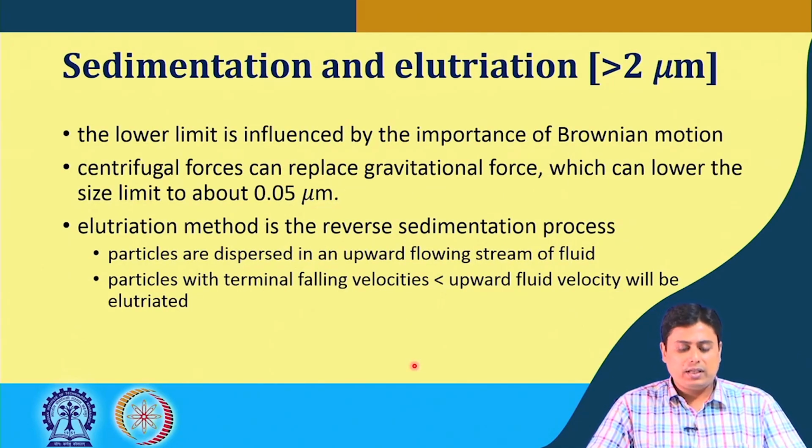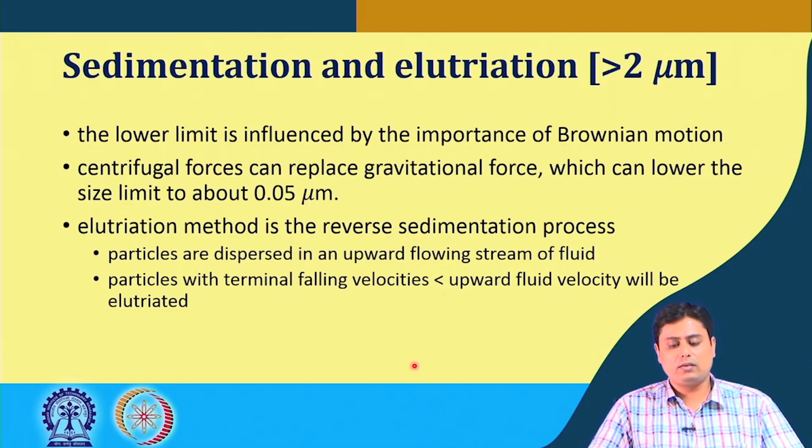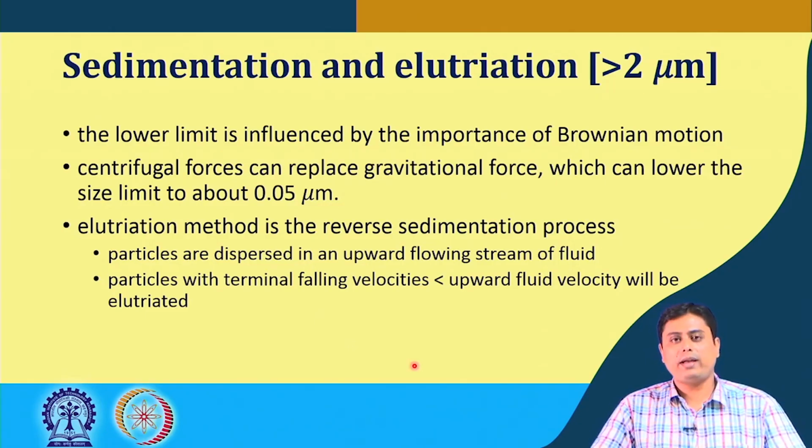The lower limit in this case is influenced by the importance of Brownian motion, because as we decrease the particle size, Brownian motion becomes dominant. So, we have to set the lower limit accordingly, or we can determine it based on the fluid property that we chose when these particles are sedimenting.